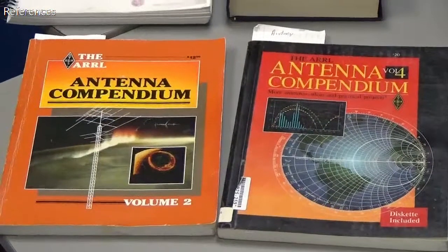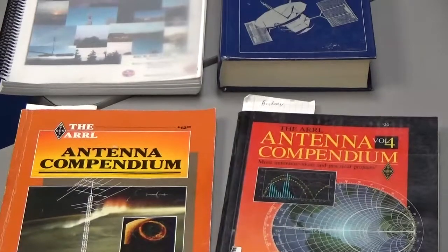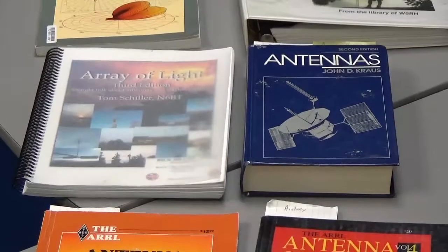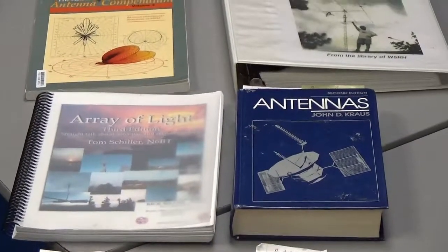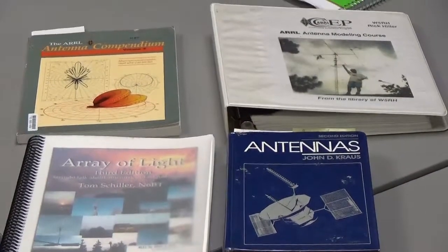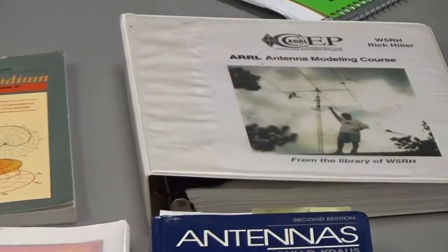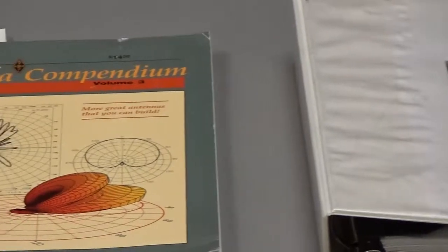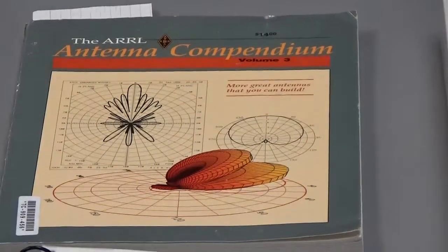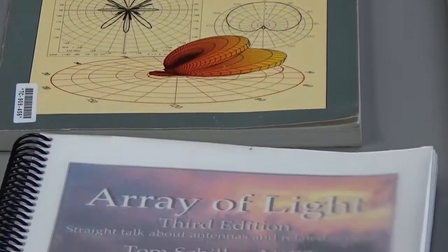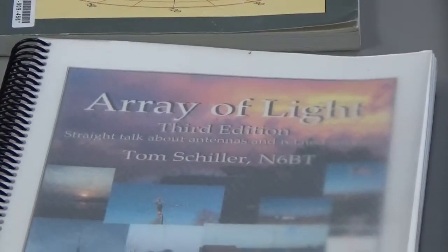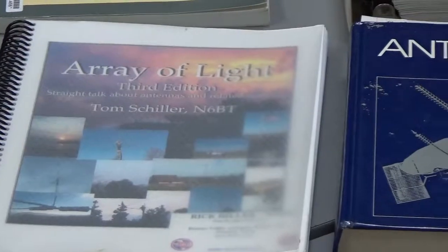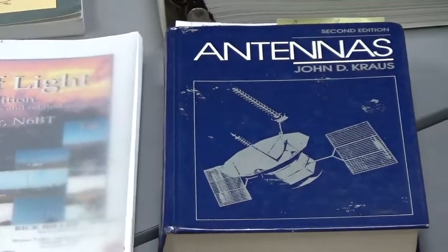Save it as something else, so that builds my little models with as little work as possible. It helps you see things like how the impedance of an antenna changes as you move it above ground. Take the 20-meter dipole, put it at 15 feet and see what it says. Put it at 30 feet, put it at 45 feet, and you'll be surprised what you can learn. Then if you go back and read the antenna book, they have the graph of that, with heights in wavelengths above the ground, and it's uncanny. It makes that graph meaningful now, where before it was kind of mystic, but tinkering with it made a big difference.